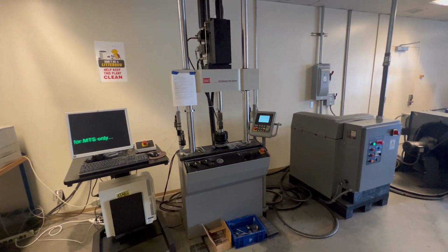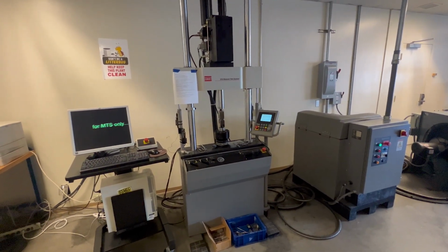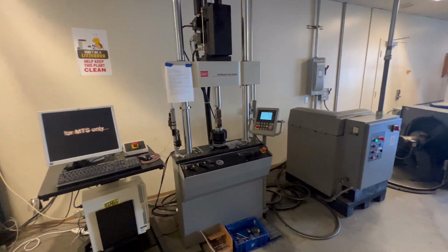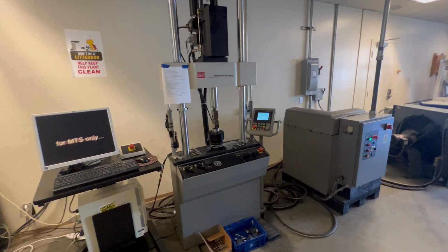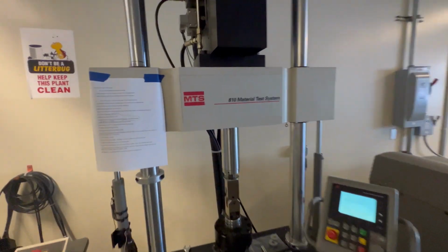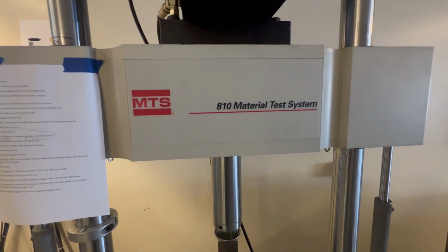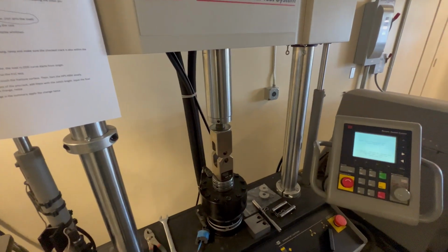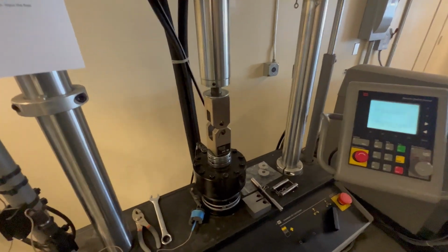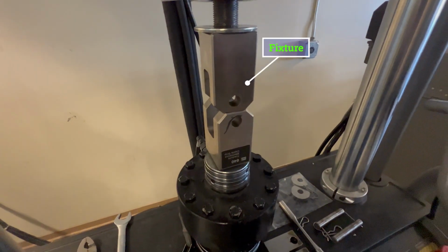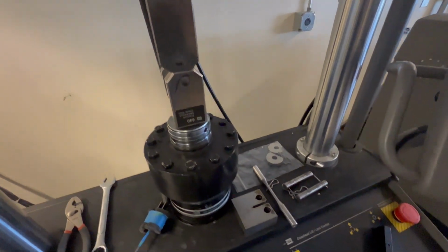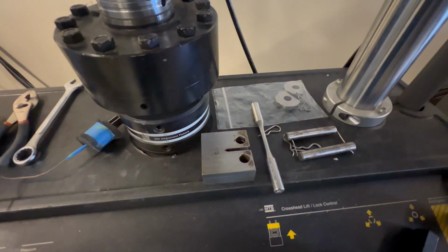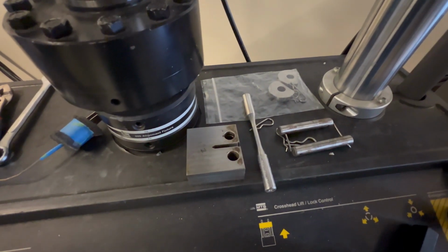Hi, in this video I'm going to demonstrate how to run a K1C test. Before running the test, let's first take a look at the equipment we are going to use, which is the MTS 810 Material Test System, also called UTM, Universal Testing Machine. Because with different types of features, we can run different types of failure tests, such as K1C, fracture crack growth test, and high cycle, low cycle fatigue test.